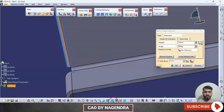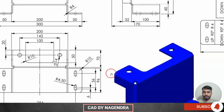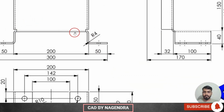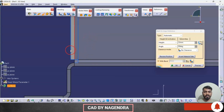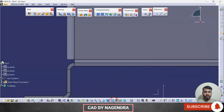You can see if I make a right side view, we'll get clarity. So this is the front view, like this. So this extra material should be exactly equal to this outer one. So this line should be exactly collinear with this. So just we can go here with this monodirectional again. Same 4 mm offset we are having. Let's say okay. I hope you have understood this step.